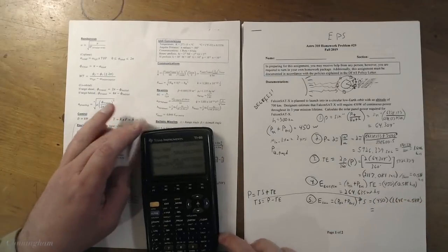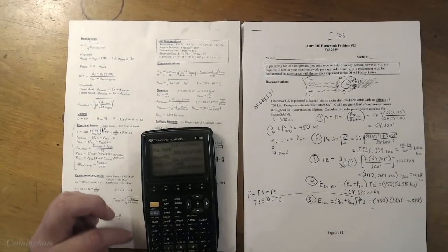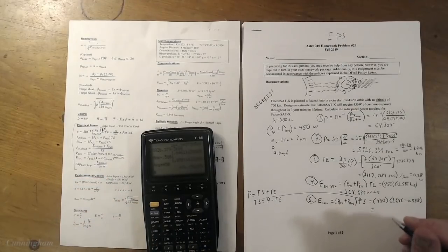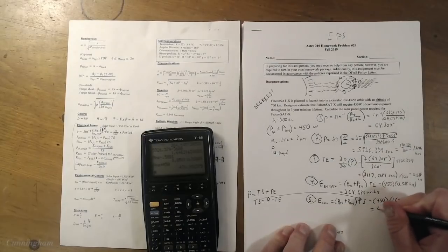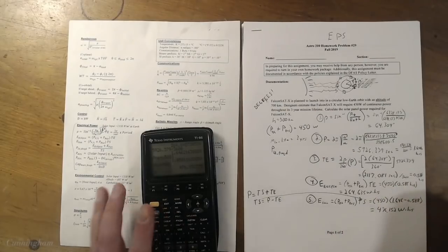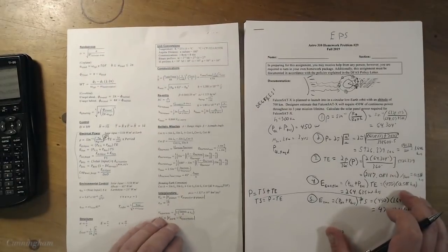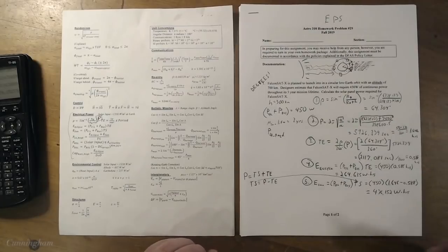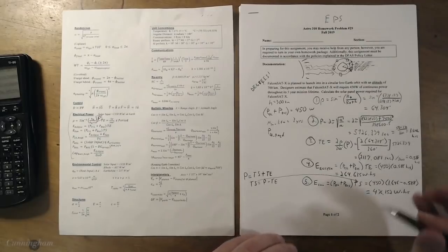We're going to get another value of watt hours here. So I find that we need about 476.152 watt hours while we're in the sun, because we've got to collect enough to charge the battery. I can't repeat that enough. In eclipse, you just have to use the battery to power the payload and the bus. In sun, you have the added burden of also needing to charge up the battery enough by the time you get to the next eclipse. So that's an important consideration.